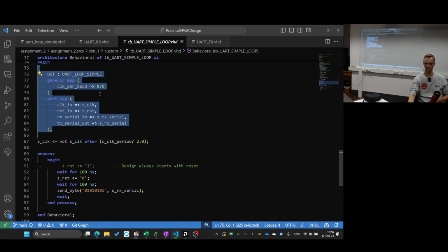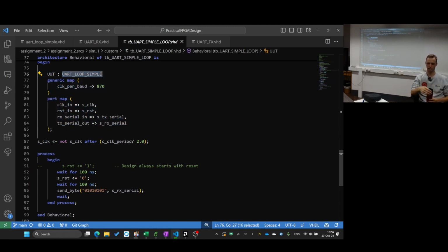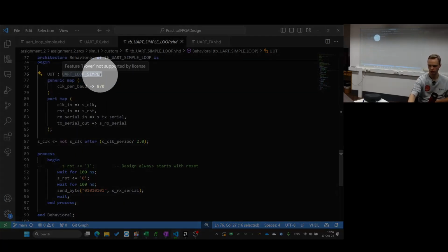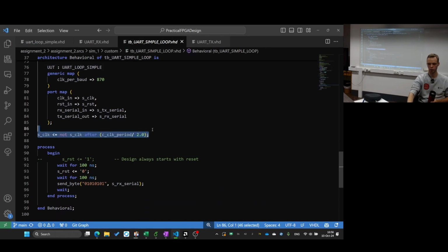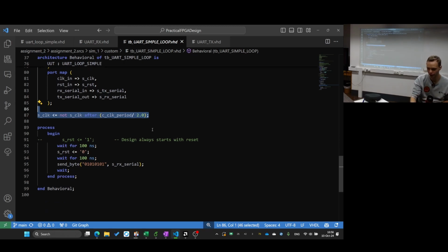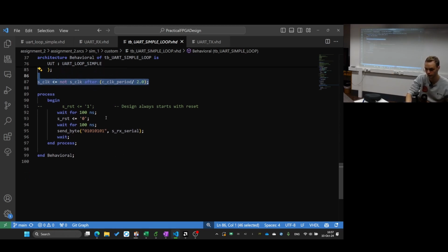So I call this generic here, and that's all I do essentially. And then I need to assign the values and the ports from my design internal. I need to have a clock. When I start writing it, sometimes I forget because it's one line which appears somewhere. I always need a clock in my design, because it is a clock-driven design, otherwise I will not stimulate it. I need to have a reset, and which is missing here? Find the mistake. And we also have send byte here, which needs to be assigned to the correct one, which is not the case here.